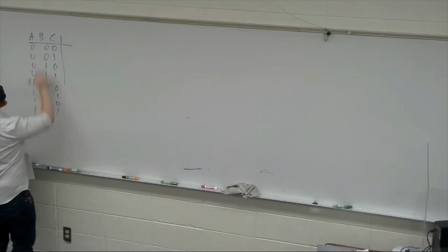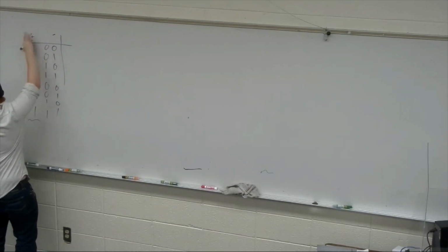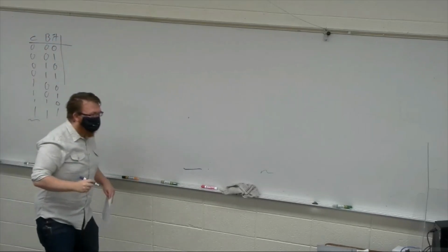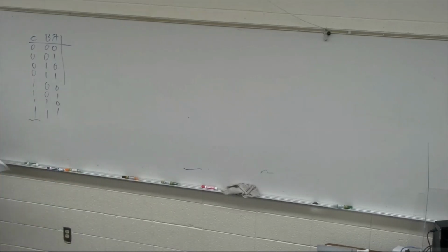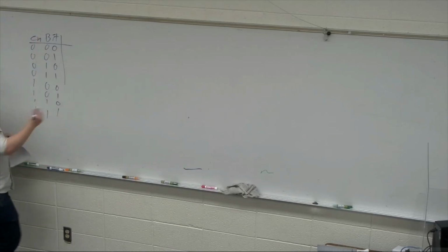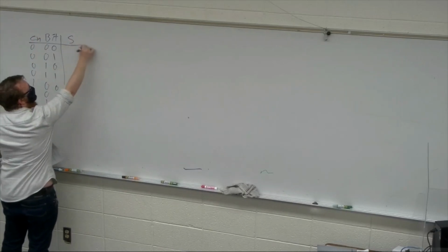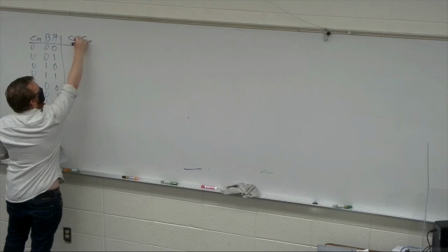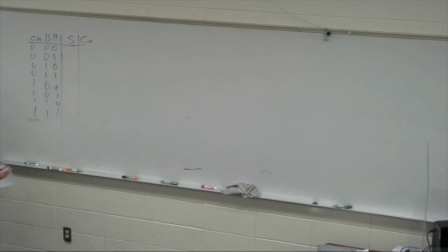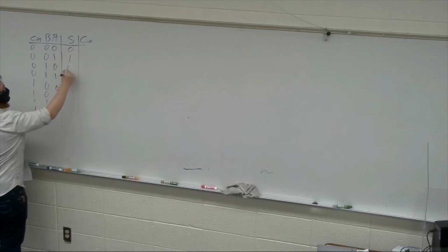And this is actually a really terrible way to do it. Let's reverse these. A, B, and C. Good, I'm actually in count. Right, so I have a truth table, and we just want to add them up. Where C is the carry in. C in. And the output is both, we have a sum and a carry out. Right, and so the sum is nice and easy, where we just go 0, 1, 1.